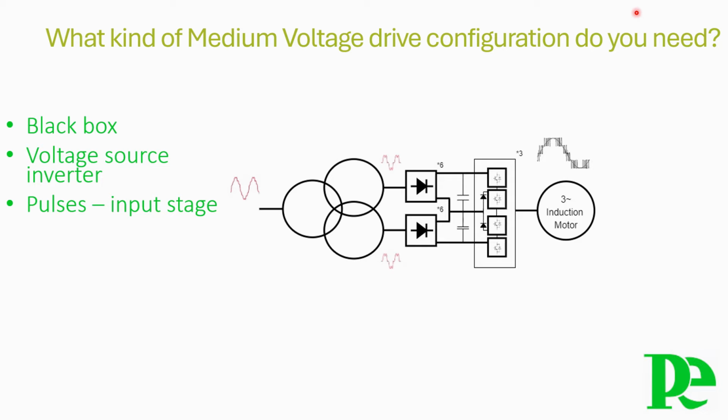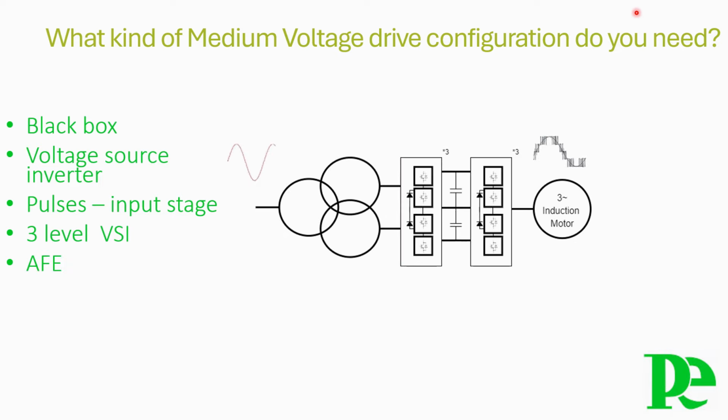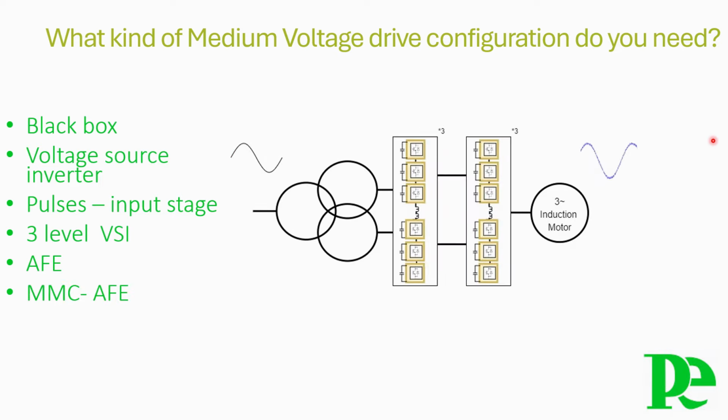An alternative to the architecture characterized by the number of pulses is the active front-end, AFE. Instead of a rectifier or direct front-end, DFE, we use basically a repeat of the inverter. The active control of the input stage enables much cleaner input power and provides even for 4-quadrant operation. Finally, combining the modular multi-level version for the AFE and for the inverter stage together realizes a high performance drive with clean input and output power.